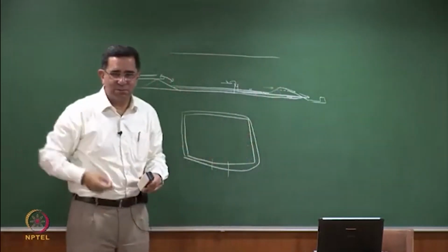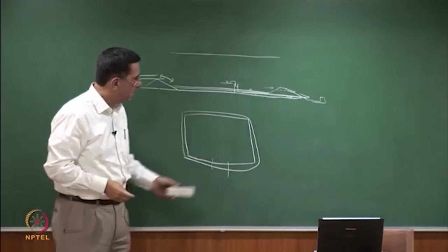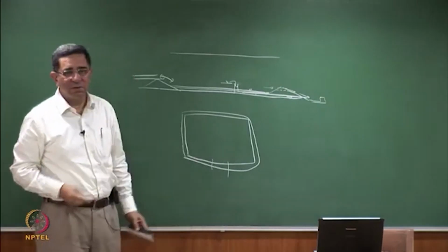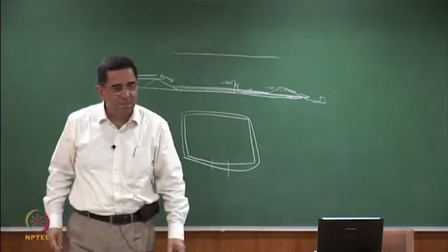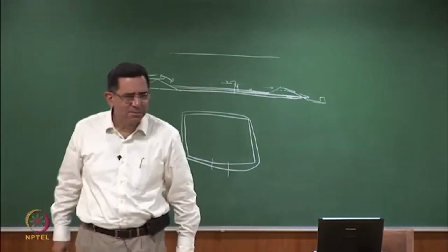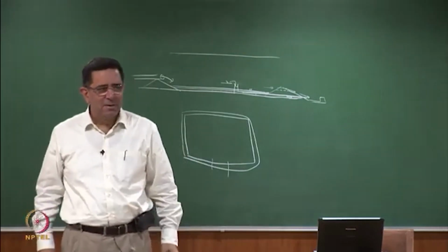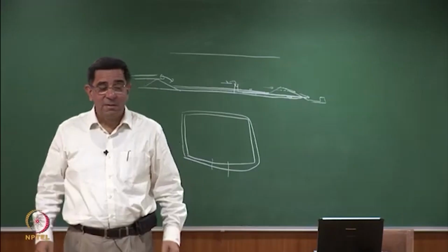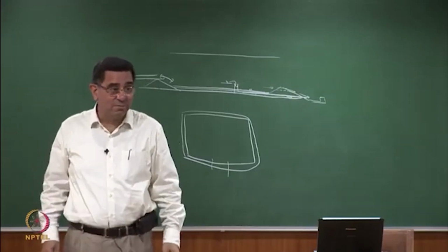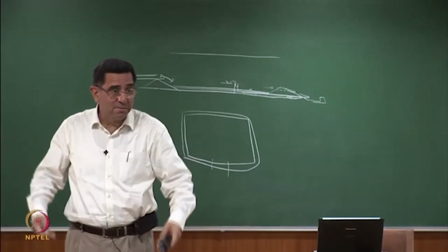What will you make it of? If I ask you to make a porous embankment, what would you make it of? Cross section. Very, very porous. Gravel, very good. Even you're bothered that gravel may get washed out. What's the next step?